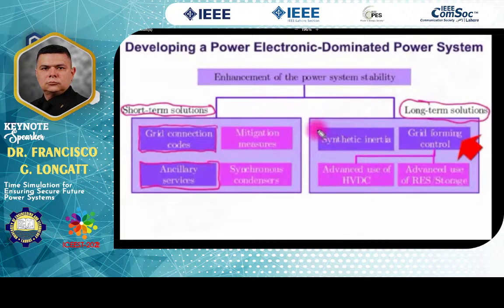Auxiliary services, there are many kinds of services, but for instance, one of the most important services that has been starting to be more and more attractive as the penetration of power converters increases is the inertia. And for that reason, in some countries, they already start to ask for frequency response, primary frequency response, from the power converters. And more specifically, in some countries, they are already asking for the inertia response from power converters. And that is auxiliary services.